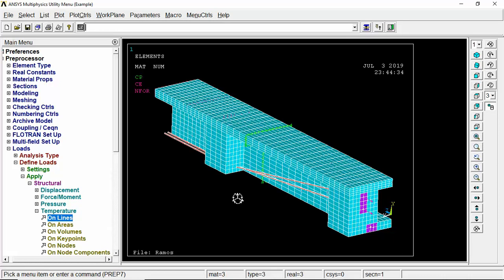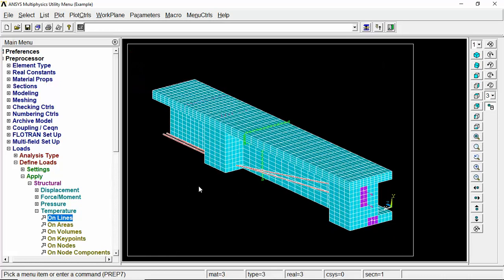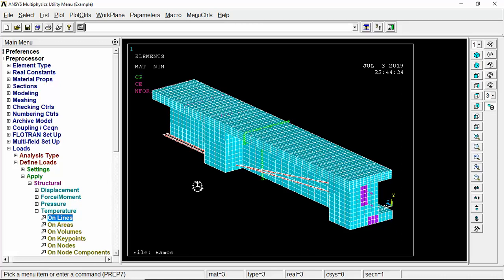But if you just apply temperature, in some cases you may face problems, because the connections between link elements are literally hinged, and you have lots of hinges in a direction, and it means that your cables are not stabilized. If there isn't any load on your tendons, they will be unstable.